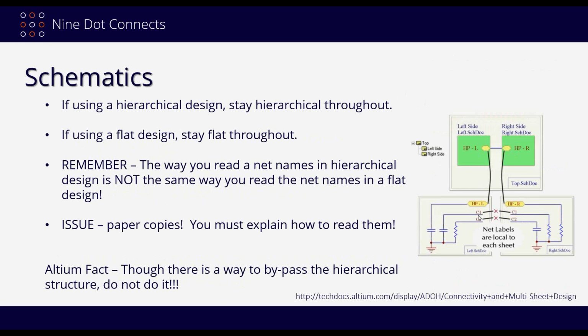But that's dangerous for two reasons, or actually the main reason is that it all has to come down to paper copies. Now if you're doing this by yourself and you've designed this and you're the one going into the lab and you've got Altium Designer on your laptop, then that's fine because Altium will be able to read the net list and you can use all its search tools to sync up between the schematic and the PCB. But if you're in a situation where you are handing off to another group and they are printing this off because A, they don't have Altium Designer, or B, they don't know the tool, they're printing off paper copies.